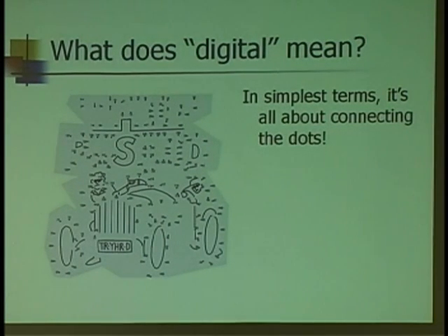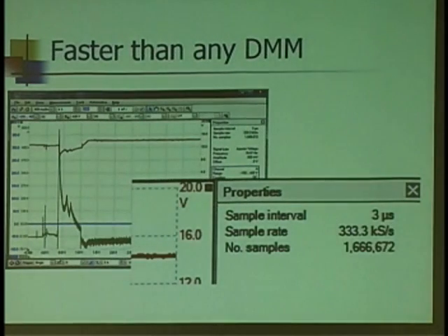And in modern scopes, we've come light years from where we started off. If you remember the old Fluke captures, especially on the vertical, how they look like a step going up, that was simply a matter of vertical resolution and sampling rates. Some of the modern scopes, this is just an example from a pattern that we'll look at in a little bit, look at what this is sampling. It's taking a sample every 3 microseconds. And all the little dots that it's connecting on the screen, well, on this capture, there's almost 2 million of them. How accurate do you think that trace is going to be?